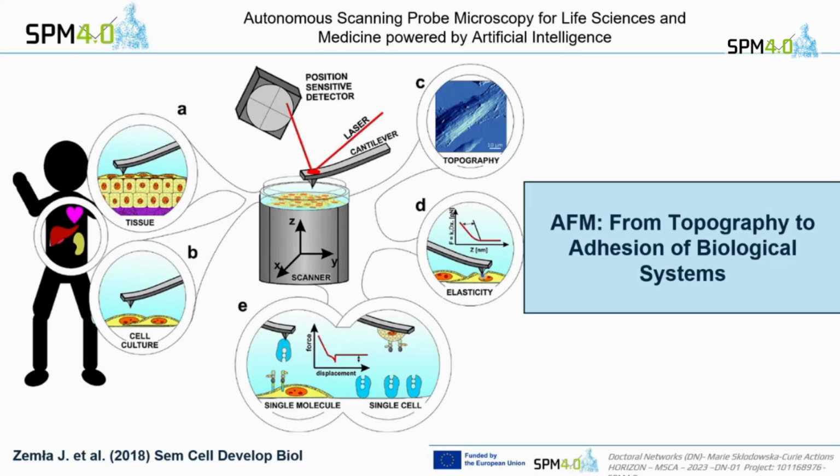Because if you have a conical probe, the information you get is more along the Z axis, so everything near the probe and more beneath. If you have a sphere, this information is more from X, Y rather than Z. And for oscillations, to avoid the bottom effect, you use small indentation depths, typically around 1 micrometer.